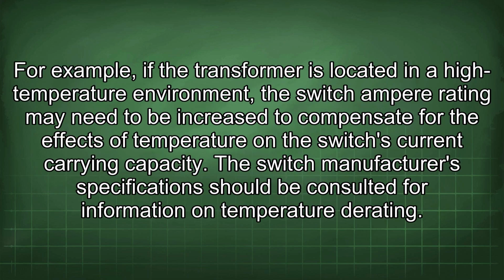For example, if the transformer is located in a high-temperature environment, the switch ampere rating may need to be increased to compensate for the effects of temperature on the switch's current carrying capacity. The switch manufacturer's specifications should be consulted for information on temperature derating.